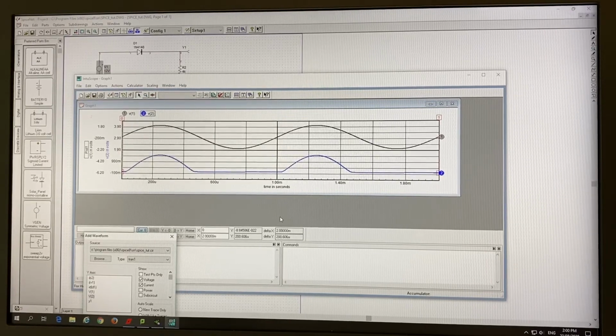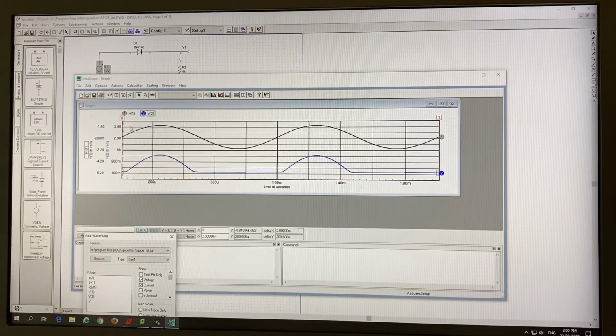But in this case, look. Input voltage on, when it's positive, I have one output. When it's negative, it's 0. Positive output on the output. Then when it's negative input voltage, output is 0. Half wave rectification, right? That's what is happening right now. So I've seen that, yeah, I've got a perfect half wave rectifier.